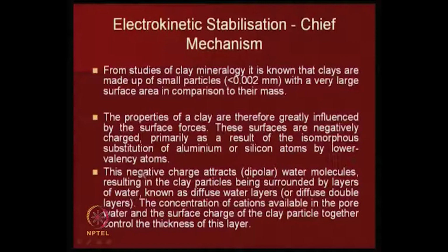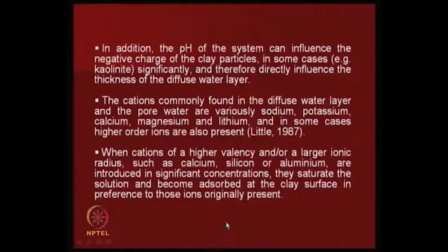And then there is a polarity of this material, and because of these properties what is called diffuse double layer formation is there. The concentration of cations available in the pore water and the surface charge of the clay particle together control the thickness of the clay layer. Actually, in Professor Mitchell's book there is an excellent description of clay soil behavior and how the diffuse double layer theory can explain the various features of the soil behavior